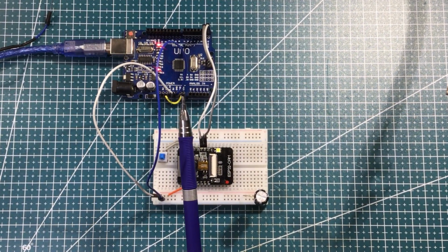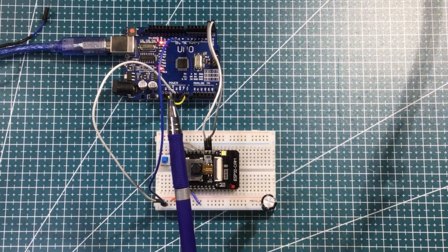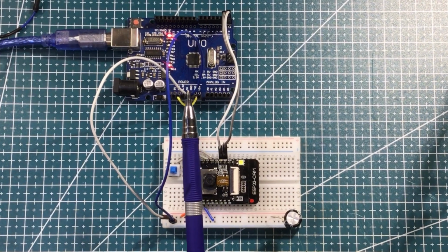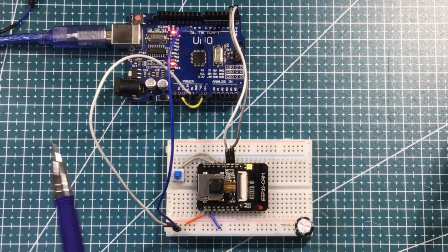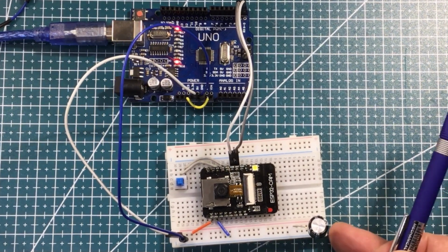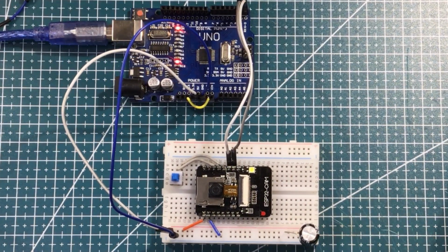The Arduino also has a connection between ground and reset, and then we've got power coming out of the Arduino, and that's just 5 volts coming to this rail down here, and a little cap in there. I think a minimum is like 100 microfarad. I think that's 1,000 that's in there at the moment.